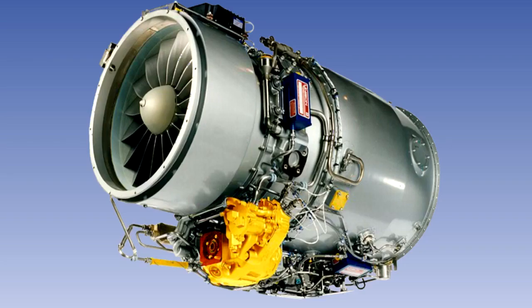Magnesium alloys are also used, their principal advantage being weight. Magnesium alloy has an excellent strength-to-weight ratio, aluminium of the same strength being 1.5 times heavier. Magnesium alloy has poor elastic properties, so its use in primary structures is limited. It is often used in the construction of gearboxes.